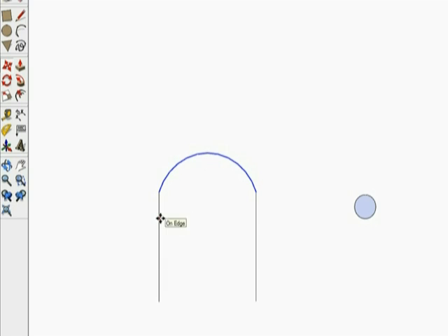It's going to bring these lines with it as well, because the endpoints of these line segments are still attached. But if I hit my Control key once, you'll see a plus come up. Now I can move it completely away, and it's separate from these vertical line segments. So that's kind of an interesting thing.